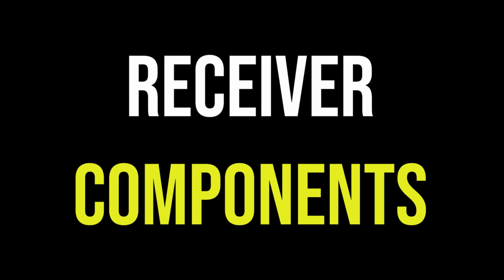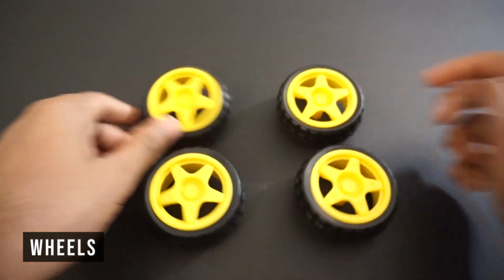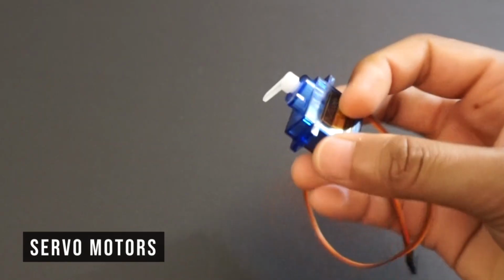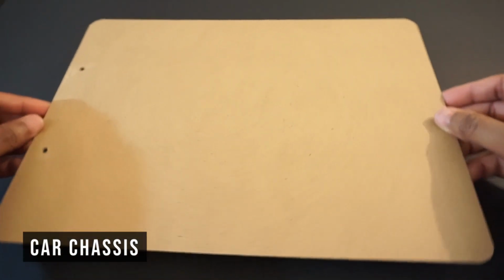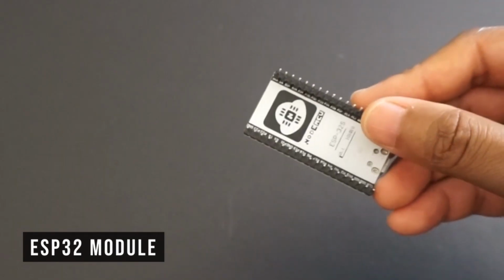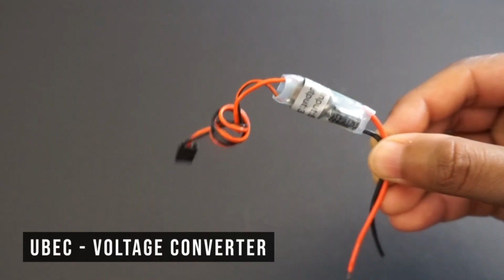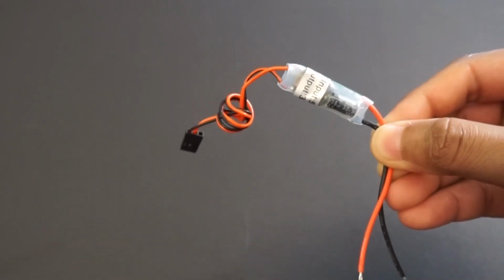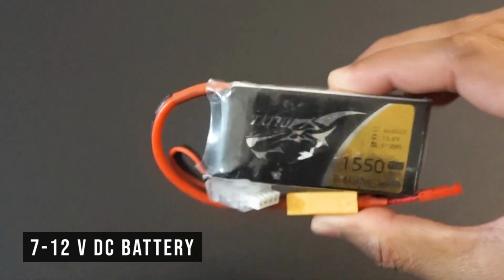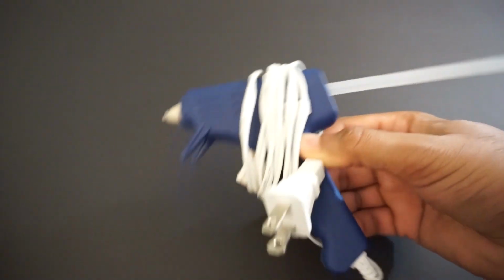Now let's take a look at the receiver. We will need 4 TT gear motors, 4 wheels, 4 servo motors, a wooden plate for the car chassis, an ESP32 module, an L298N motor driver module, a UBEC to provide 5V to all servo motors. You can also use any buck converter. A 7 to 12V DC battery, in our case a LiPo 3S battery which will provide enough current, a glue gun and a few jumper wires. Let's assemble the car now.